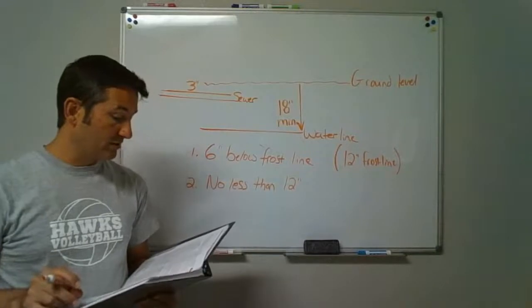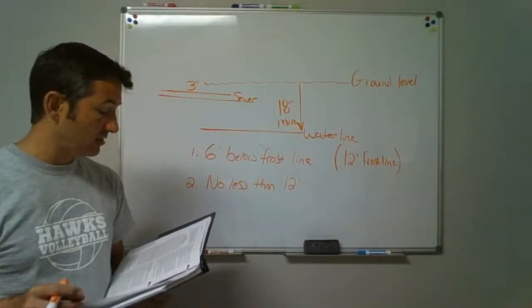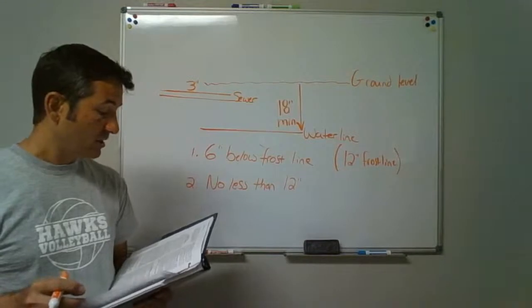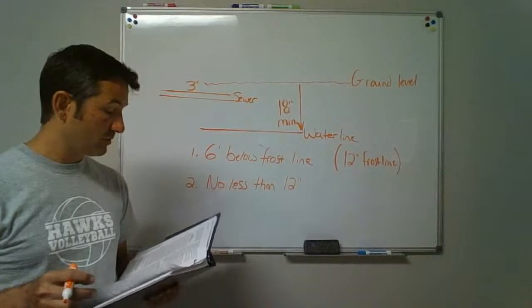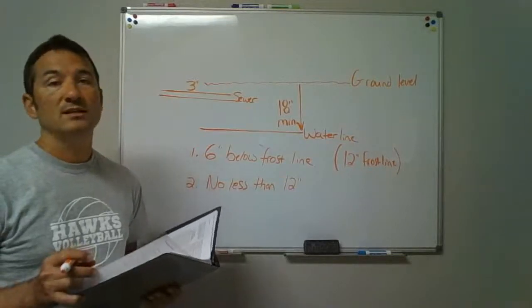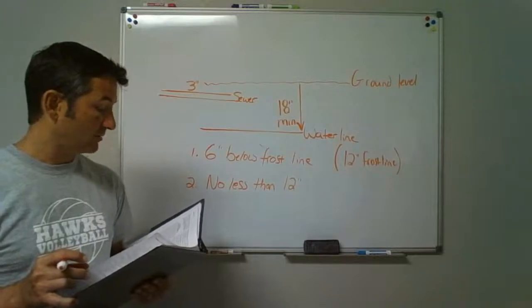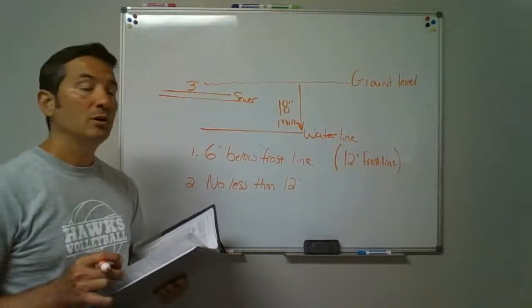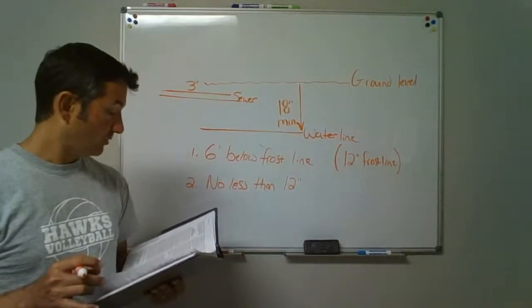Waterproofing the openings. Joints at the roof and around vent pipe should be made watertight by the use of lead, copper, galvanized steel, aluminum, plastic, or other types of flashing or flashing materials. Exterior wall openings should be made watertight as well. Anytime we send a pipe through, we need to seal it up and make it watertight. When we go through the roof, we're going to put a roof flashing on there and make that watertight around that pipe.